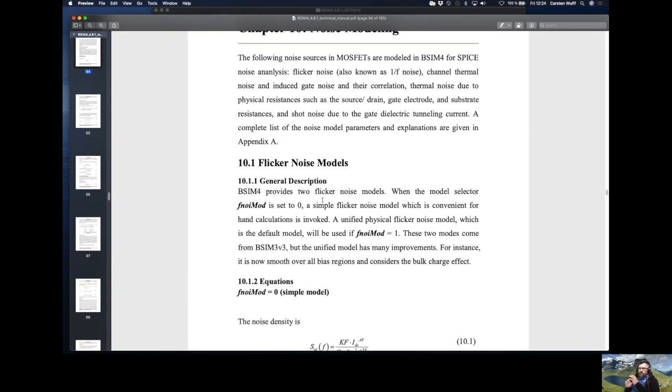It's simply completely different. And this is usually due to things like generation recombination noise and the fact that it is not in the SPICE model. So you actually need to know a bit about the physics and then basically guess what's going to improve and cross your fingers and test. Okay, let's get back to the presentation.